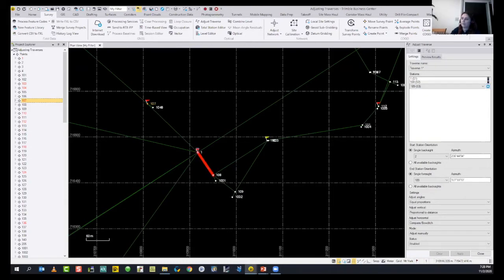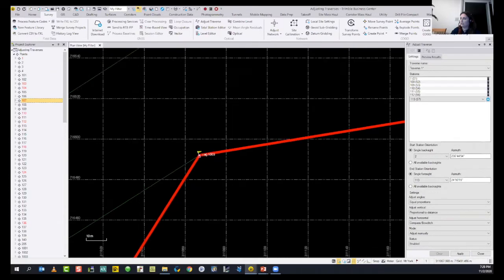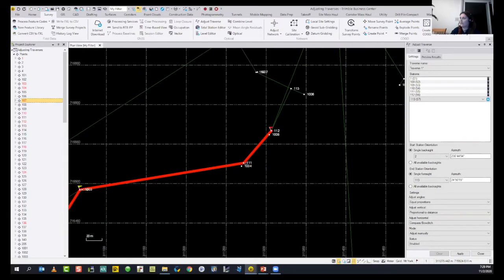It's going to start drawing the traverse. And I'm going to display other options. I don't want to end my traverse with the start station, so I will continue with 109 and hit on that. There is no other possibility, no other stations for those points, 110, 111, 112, but it stopped at 113. This means that I can pick one of those. And I will continue it with 118.